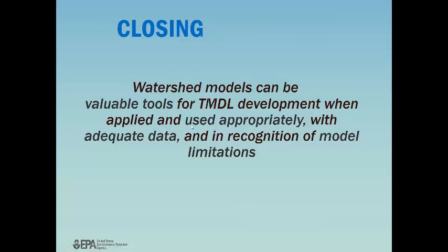So anyway, I wanted to leave a couple of closing messages with you: that watershed models like HSPF can be valuable tools for TMDL development, but they do have to be applied and used appropriately. So some guidance and training in the use of the tools is really highly recommended. And make an assessment as to whether you have adequate data to do a reasonable calibration of the model. And you do need to recognize that the models have limitations. There are things that some models cannot adequately represent that may be important in your particular situation.